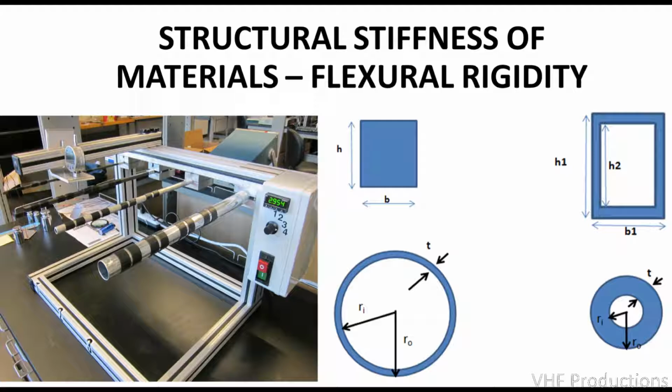The purpose is to demonstrate that stiffness in a component can be achieved through two different paths. One path is by changing the material of choice, where the materials have different elastic moduli. And the other option is to change the geometry of the material used in the component or structure so as to optimize the structural stiffness of the component. Of course, as an engineer, you have the option of combining both changes in elastic modulus and changes in the component design, to optimize the overall structural stiffness.